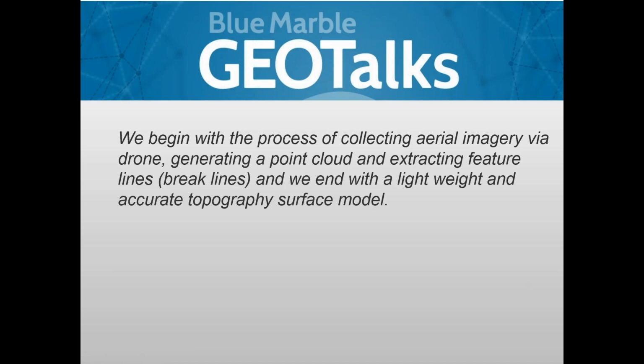In summary, we're going to begin with the process of collecting some aerial imagery via drones, generating a point cloud, and from the point cloud, we're going to extract feature lines. Some of us call this a break line, and then we will end with a lightweight and accurate topography surface model.